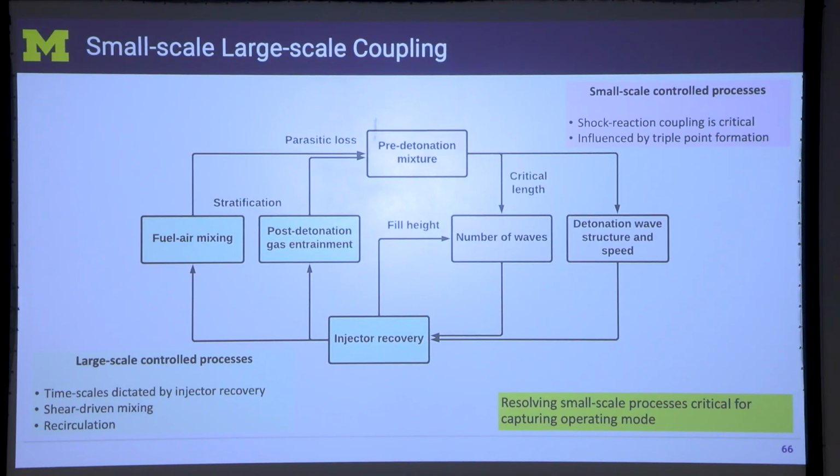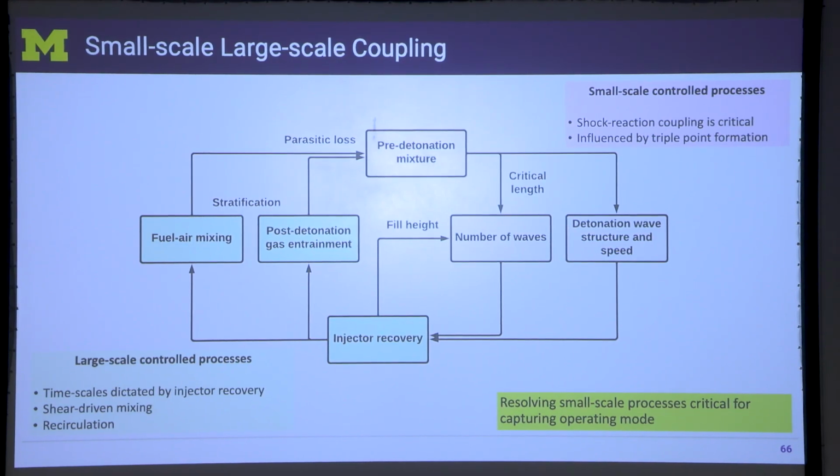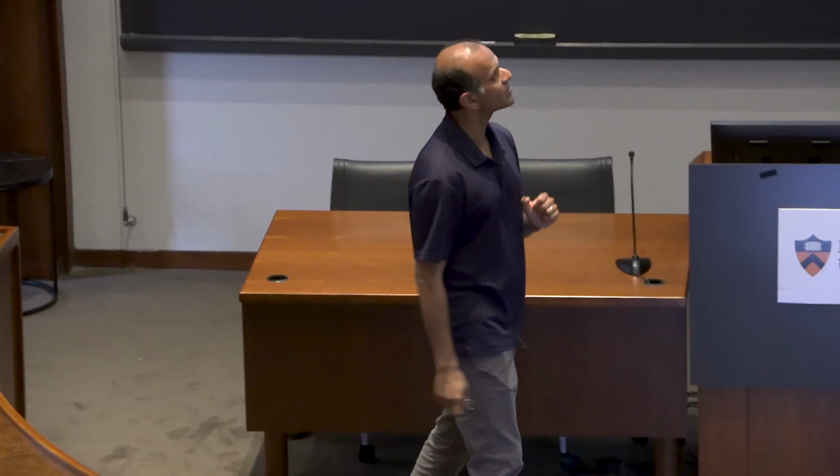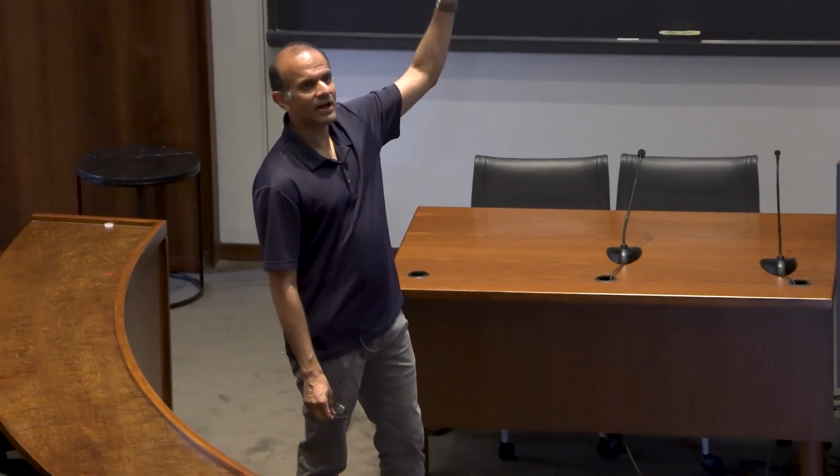I know that if I have annular geometry and I put in fuel and air, I can somehow get it to be a detonation engine. So it will have a moving detonation wave. But what I cannot predict ahead of time, with all the computers in the world and all the lasers that I can have, is how many detonation waves will operate for given operating conditions. What speed will they move with? They will not all move at CJ speeds anymore because it depends on the mixing pattern. So they'll move a little slower than CJ speed, sometimes a lot slower, like only 50% of the speed. I don't know that speed, and I don't know the width of the detonation wave. How large is that high pressure region behind that shock wave? So it leads to this complex pattern. There is some link here, and we do not know what this link is.